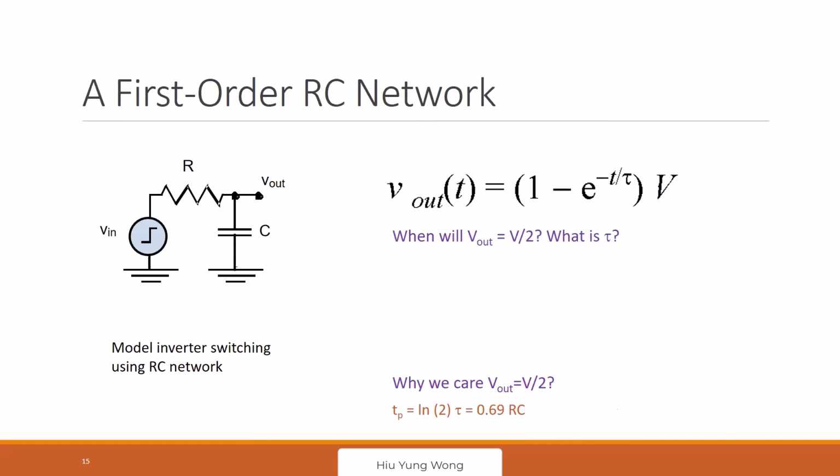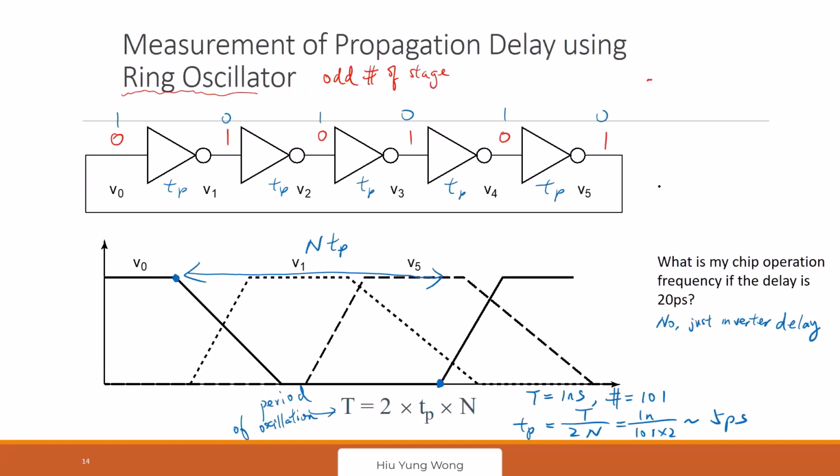I have a question about the clocks. I know that there's a circuit called a phase lock loop to provide the clock signal to the chip. For the digital circuit, what kind of oscillators are they using? Ring oscillator for the phase lock loop? Oh yeah, you can use different types of oscillator. Ring oscillator is one of them. But the phase lock loop is just to generate the oscillation.